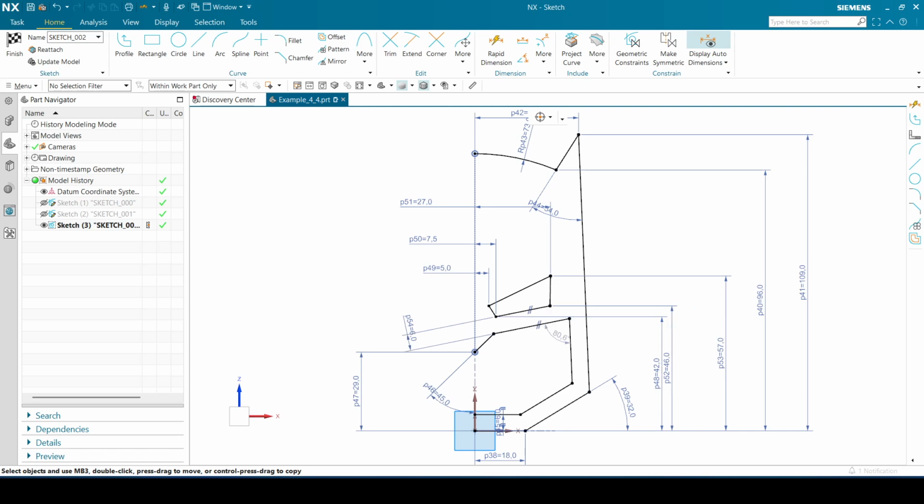I almost thought it was that 6, but no, these are still parallel to one another by virtue of the offset. Now I realized I just looked at the sketch properly and saw that this one is in fact vertical. So if you look clearly at the sketch, you'll see it is actually vertical. The sketch is just a bit small, so I first missed that. There we go. So now it is fully constrained.